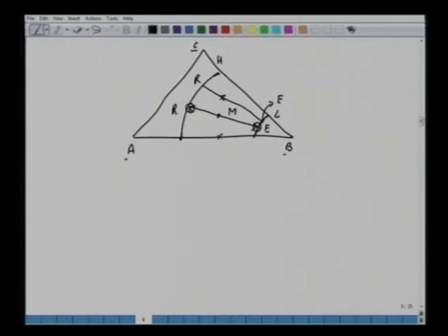If I choose here, all it means is still there is a tie line, except there is no amount of C here. If I choose any mixture of B and C, all it means is there is no A here, and we have this tie line. So there is a tie line like this, like this, like this, which represents equilibrium between the raffinate phase and extract phase. One can plot this.